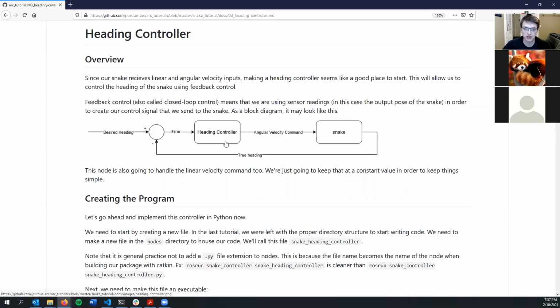And more specifically, we're going to be using something called a bang bang controller. If you've heard of a PID controller, that's another thing that you could use here. Or you could use a lead lag controller if you wanted to get technical. Or you could do all sorts of stuff. You could have a machine learning algorithm here, but a lot of that is really overkill for what we need. So a bang bang controller, all that it does is you just have two absolute values that you go back and forth between. So your output is going to look like a square wave.